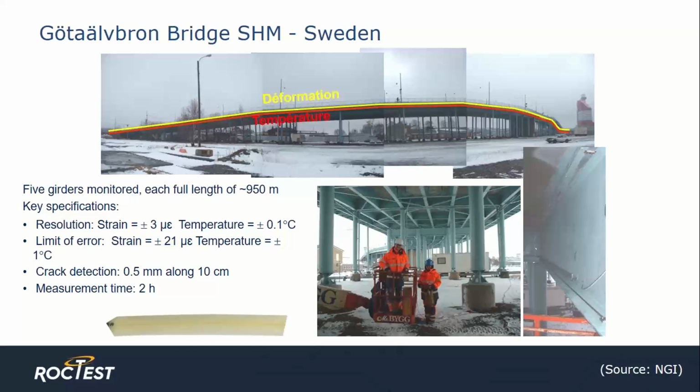The recommended specifications from the client were very stringent. The key specifications were resolution. The strain had to be within 3 microstrain, the limit of the error within 20 microstrain, and the interrogation frequency was every 2 hours.